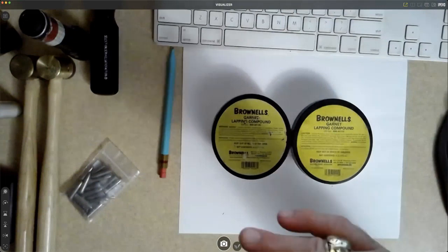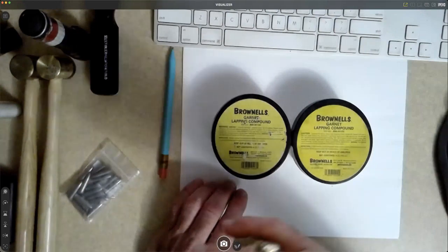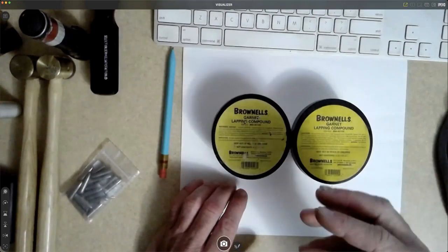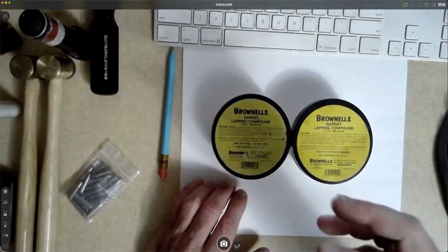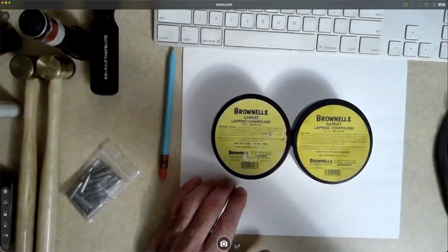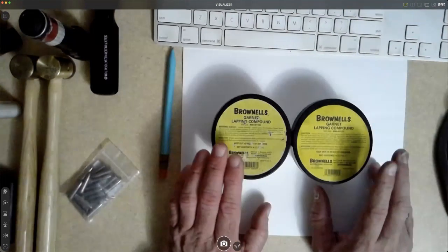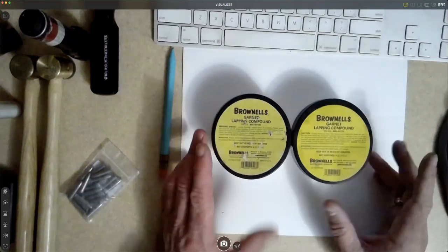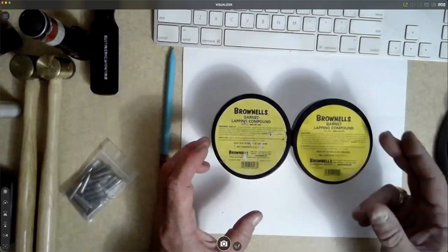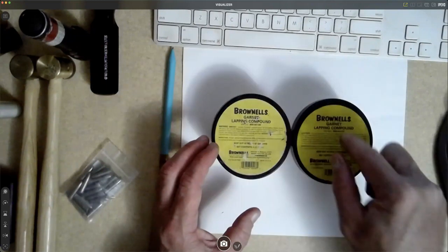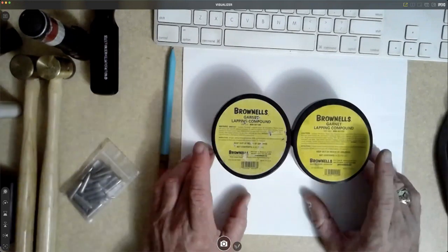I like to use them a lot on the inside of the chamber because it's rubber. It gives a real solid initial polish, and then from there you can step it down. Those come in different grits based on color. When you buy the Cratex kit, each one of the blocks will tell you what the grit is.